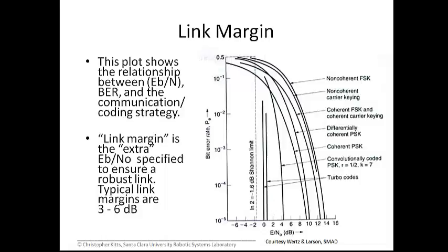Move over to the left a number of curves, and you see one example, down in the lower left-hand portion, kind of the third plot to the right, is something that the arrow shows. It's called convolutionally coded PSK, or phase shift keyed. And if you remember in command and data handling, we talked about convolutional encoding being an error detection and correction technique. And the R and the K values give you some specs on the convolutional encoder in terms of its structure. But if you use that, then you can detect and correct some of the bit flips. And it shows you a different relationship of performance.